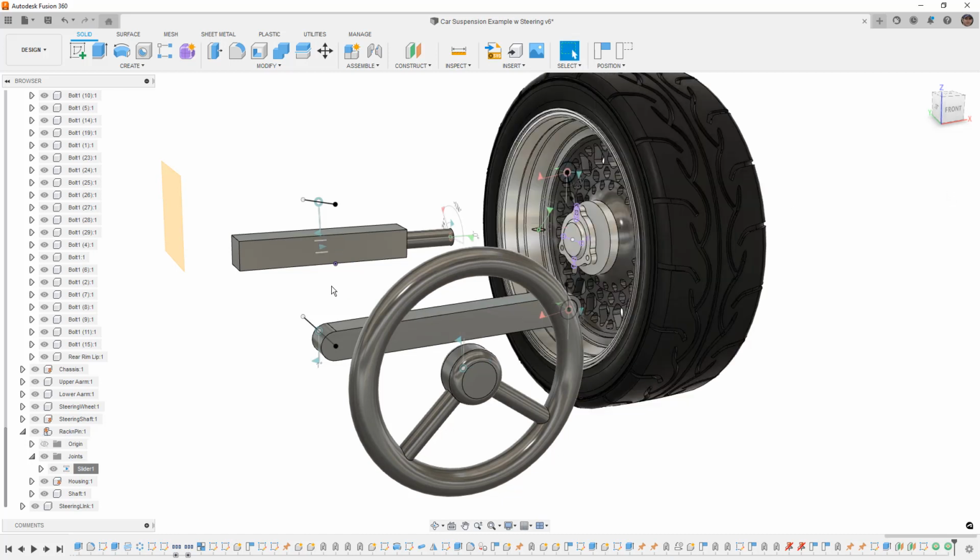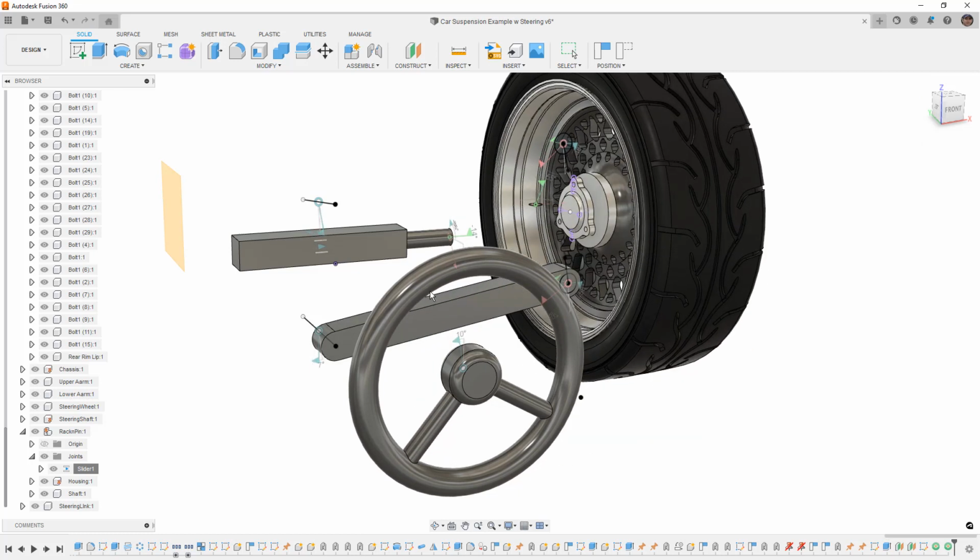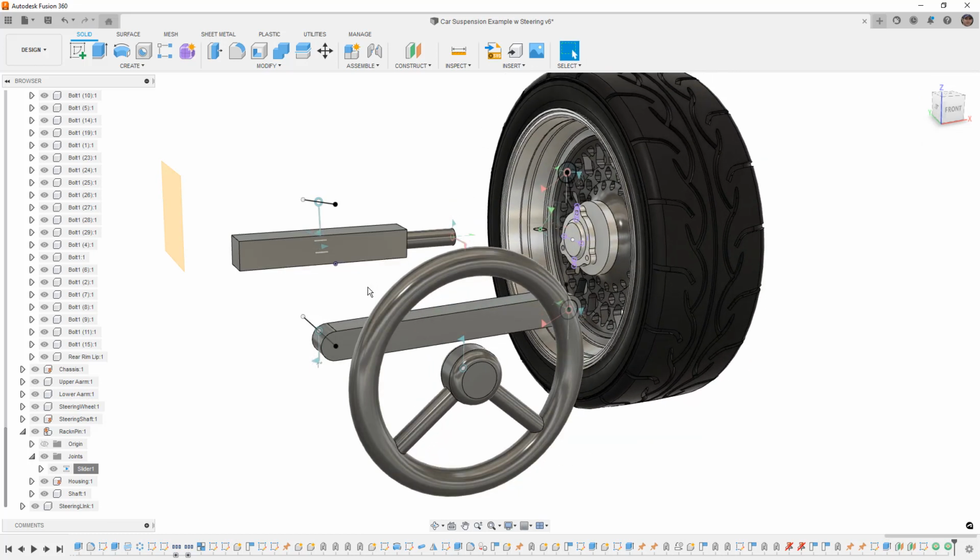Keep in mind as well, the way that we set these designs up, you can always go back and move these components around, restructure your sketches, and change the suspension geometry. Now, this one was the next step after we did the initial suspension setup with just sketches and components, without worrying about all these solid fake bodies for the steering wheel and this other stuff. Those were set up in a way that we were looking at just the basic geometry points. That's a really good stopping point for you to figure out that suspension before you progress into building these 3D models. So you can always go back, tweak those points, move them around, and see how it progresses. But again, it's very much a brute force method. You have to measure everything out manually.